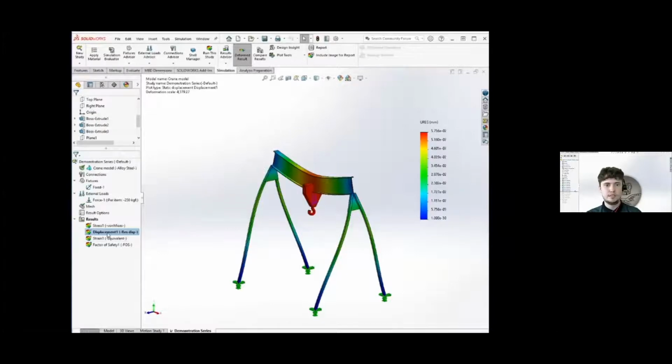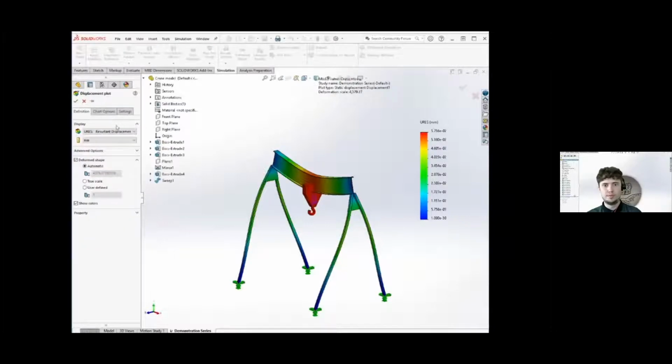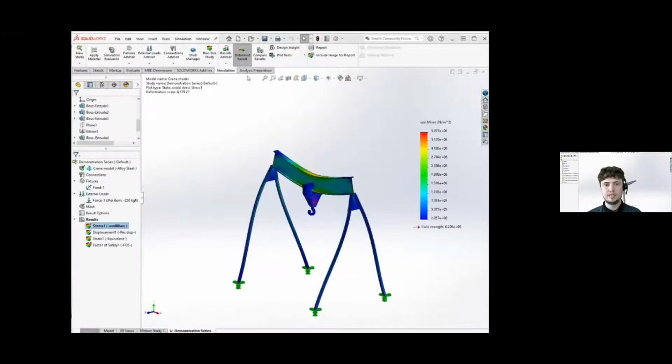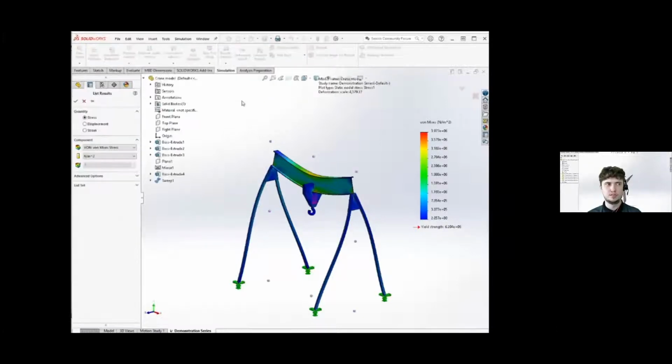The factor of safety is something else we can determine. The crane is definitely well above the minimum factor of safety, which will be specified by the manufacturing design. And here we go. This is what it would look like if it deformed in the real world. As you can see from this, the maximum displacement is negligible, which helps verify that this design would be safe in the real world if it was produced using alloy steel, as it would not deform very much.